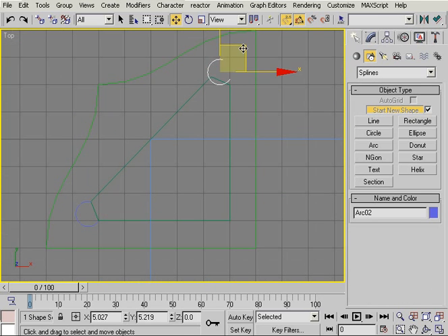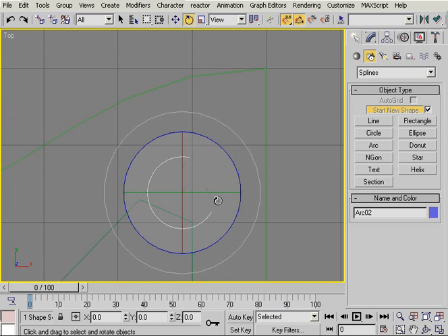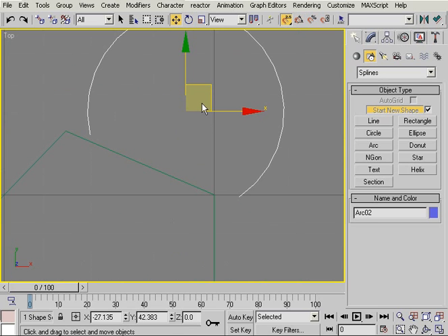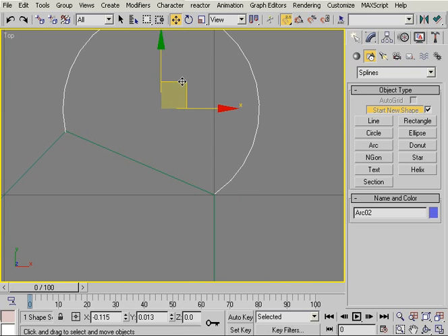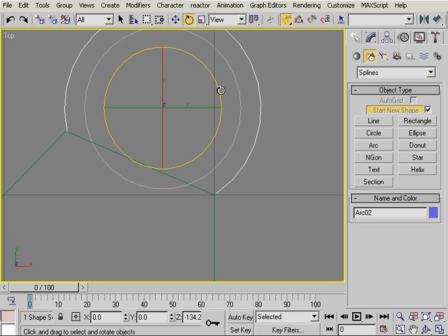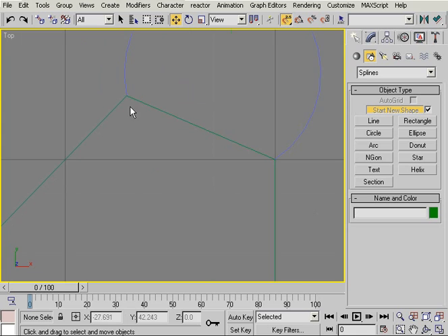I'll press shift and go choose an instance, and here I'm going to rotate my arc so that it coincides with the other part here. Okay, and then I'm going to move it close to one end. Alright, maybe it needs to be rotated a little bit more, so I'll give it a very slight nudge. Okay, and I'll go and choose snap to vertex and go like so.